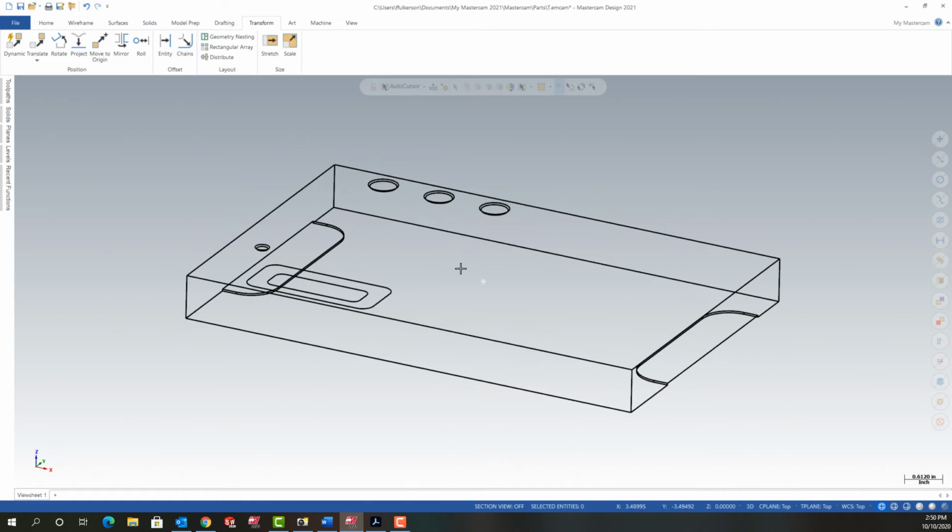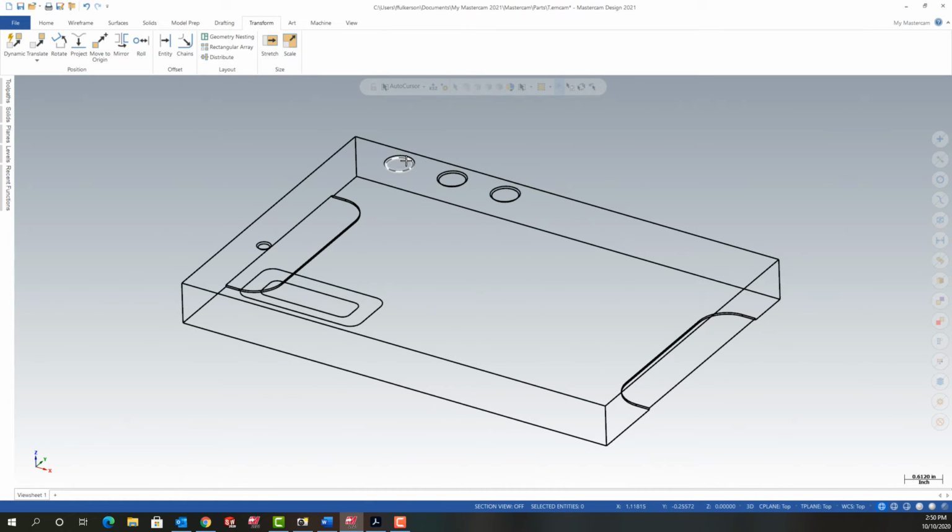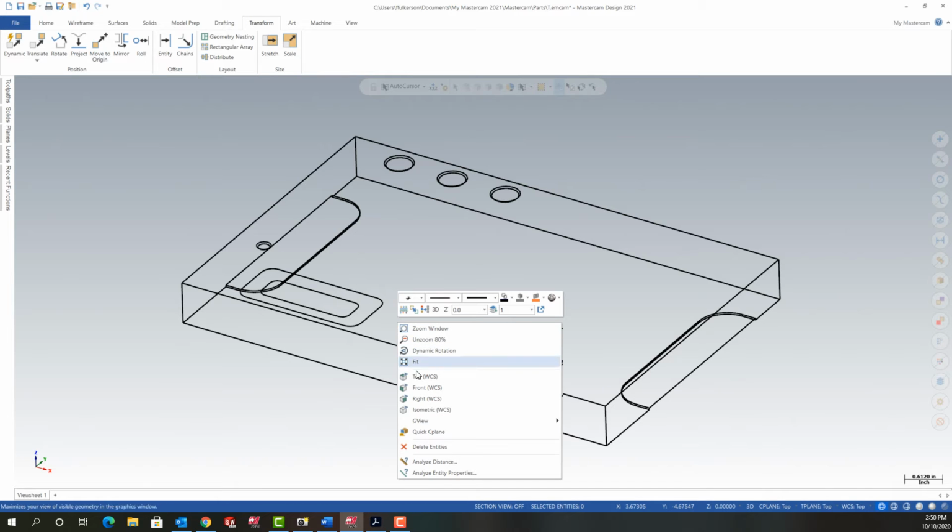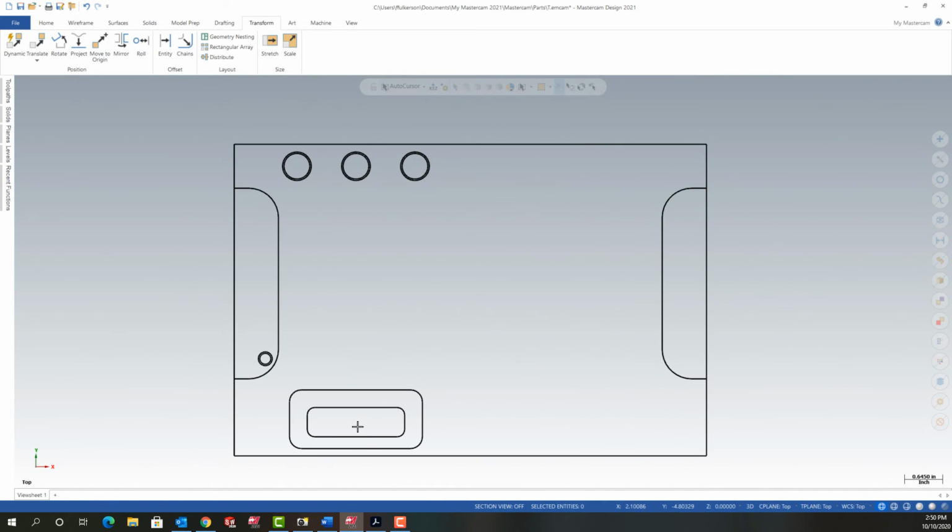Okay. Now when I translate them to depth, it's this circle I need to select to translate, not this one. Same thing here, this circle, not this one. And you guys will have created some of these as half circles and joined them, that's fine. So the next thing we want to do, I'm going to go back to the top view, is this pocket.